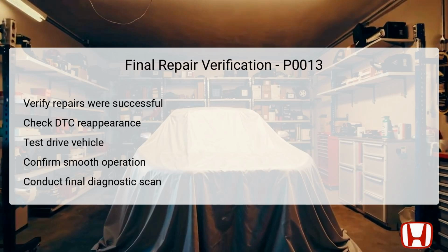Start by checking if the DTC reappears after completing repairs, using the Honda Diagnostic System to perform a reset on any codes flagged during the troubleshooting process. Then, a test drive is necessary to properly assess the vehicle's performance under various conditions and speeds, ensuring that smooth operation has returned, free from any warning lights on the dashboard.